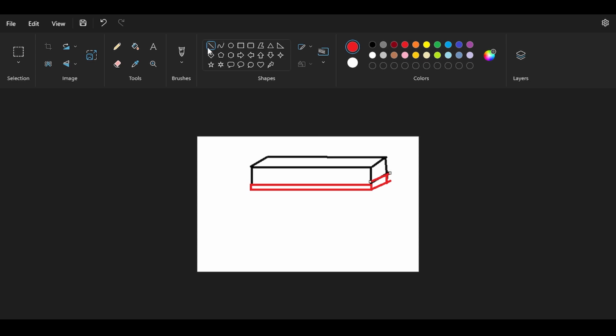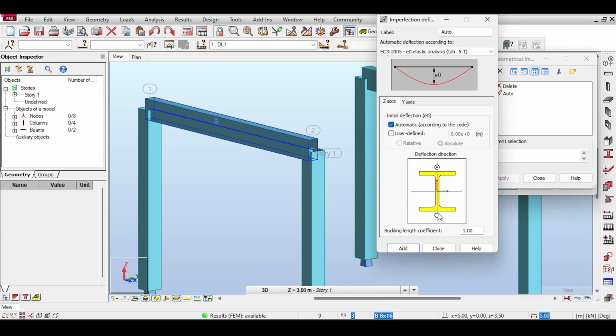Now when you cast your concrete, because of the weight of the concrete, there is a high chance that the formwork will bend a little bit under the weight of the concrete. Now that's totally fine, and when we do our formwork analysis and design, we actually design the formwork and design the spacing of the supporting elements of the formwork, but nevertheless, the formwork will sag under the weight of the fresh concrete, and the sagging goes down. So obviously, the imperfection that makes sense for concrete is down.